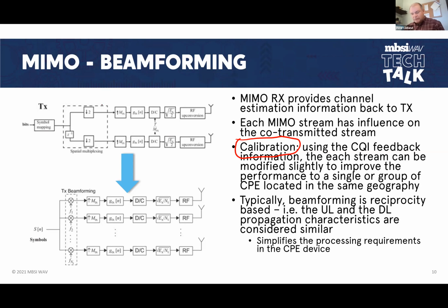When the transmitter speaks, the receiver hears, and the filters, the equalizers, everything has to operate within particular limits. That's called calibration. If it fails any of these, if something's out of limit, for example if one stream is non-existent at the receiver, the CPE might report a calibration error in the log, but in fact what it's telling you is that it doesn't see half the signal. So calibration is an important function, and it's one of the reasons why booting up a modern base station takes some time, because it goes through this whole process during boot up. So we need to have this.